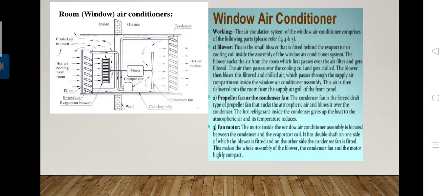Direct sunlight tends to increase the condensing temperature and operating cost, and thus reduces the efficiency and capacity. For the installation of a window air conditioner, there are some steps. First, remove the air conditioner from the crate. Also read the installation instructions provided by the manufacturer.